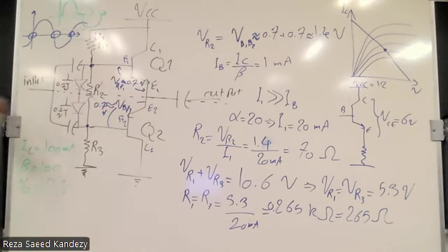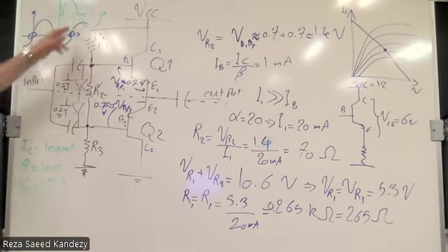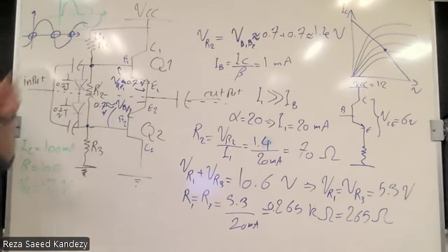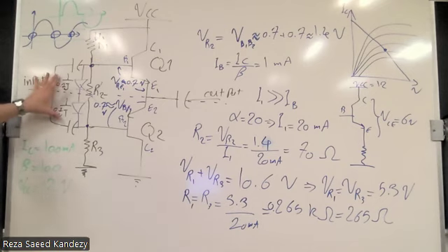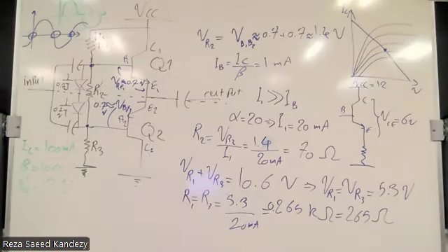So theoretically, this would eliminate this distortion. In reality, it just decreases that distortion. So if you see in your oscilloscope that you still have distortion, that's okay, and it's very normal. It's because of the real versus theoretical voltage across the diodes and the real base-emitter threshold voltage for both of the switches.